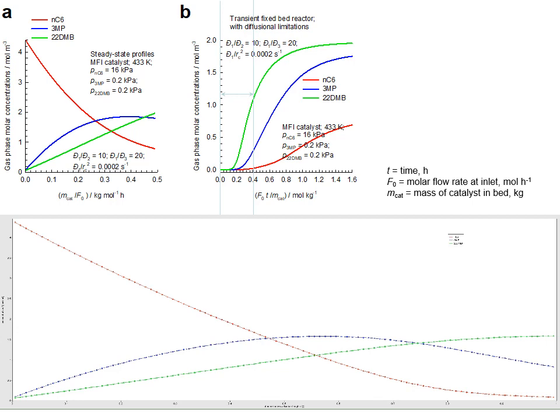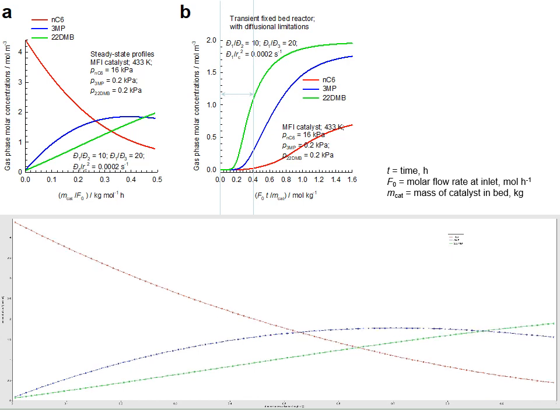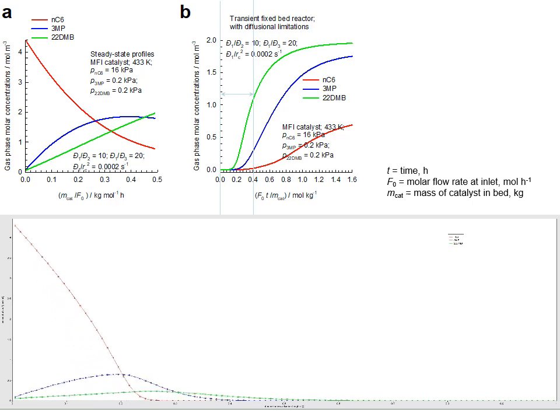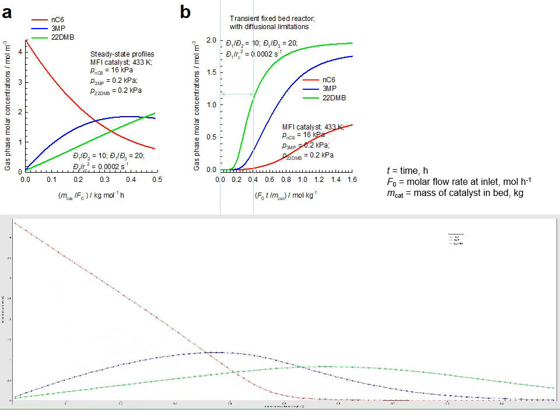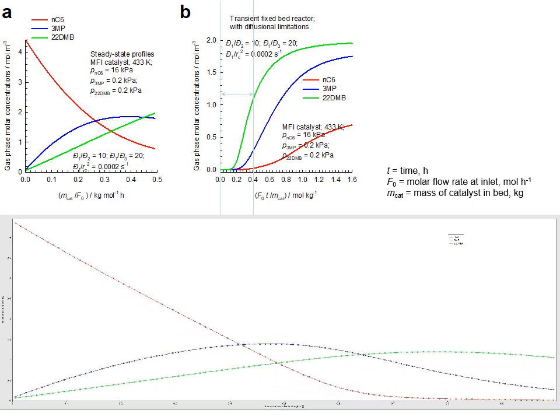If we continue and allow steady state to develop, then normal hexane will also leave the fixed bed, and the advantages of transient operation cannot be exploited. So I leave it there.